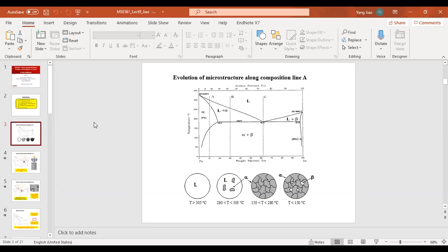the more realistic scenario, where the solidification front cannot remain a plane for all time, and if you have perturbations on this solidification front, whether those are going to grow or shrink, right? And we showed that the Gibbs-Thompson effect plays a key role in those cases, and we did a very elegant analysis to demonstrate an important phenomenon that is commonly seen in all solidification processes, which is related to the wavelength selection. And by now, I think we can understand all the beautiful patterns that you see in nature produced during solidification are underlined by the Gibbs-Thompson effect.